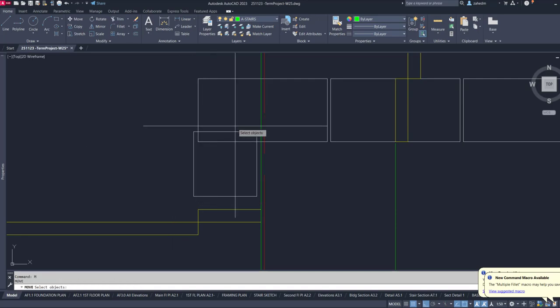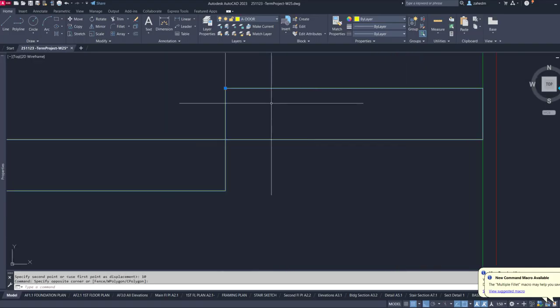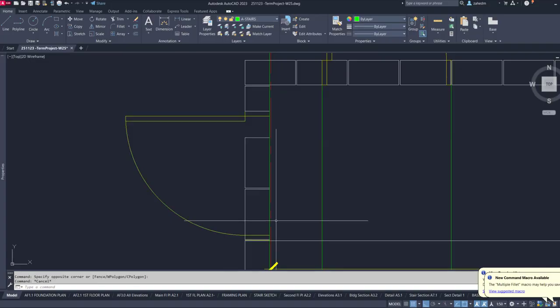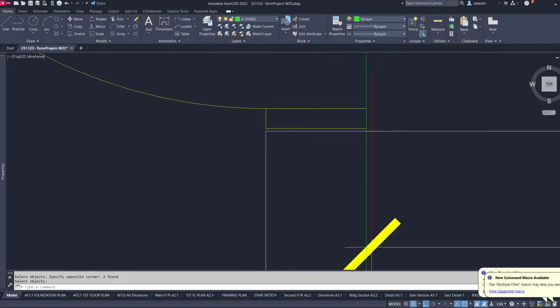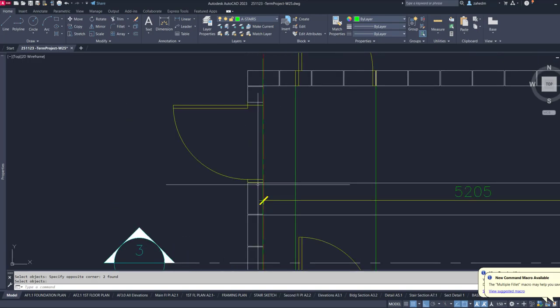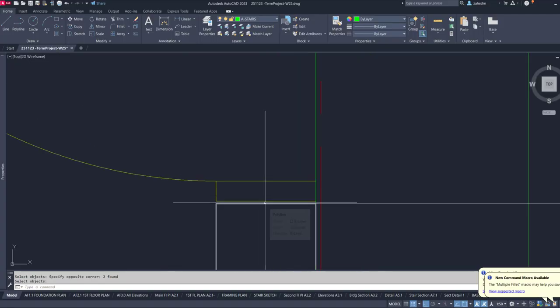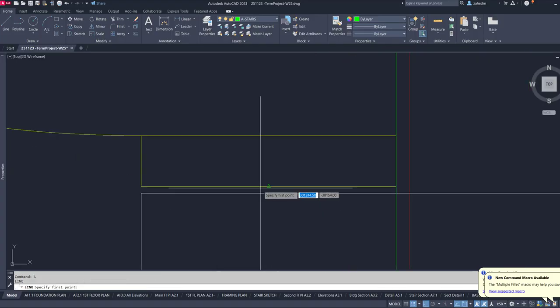Okay, and then move from that corner to here, and then move it 10 for the sake of mortar. And then as you see, my door is exactly sitting where it needs to locate. These two other blocks should be removed, and then now here we have exactly the correct size for this door. It sits where it needs to be seated, and if I just take a distance from here to here, it's only 5 millimeters. It is possible to even this out.